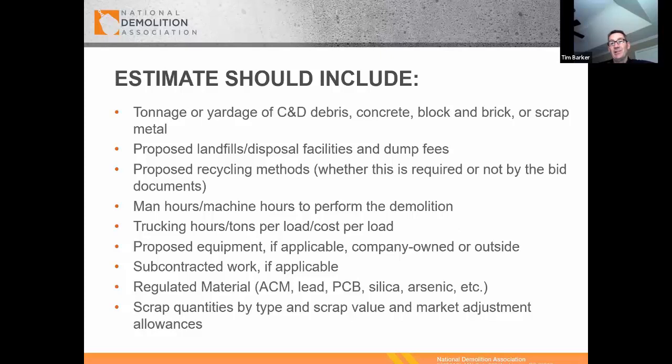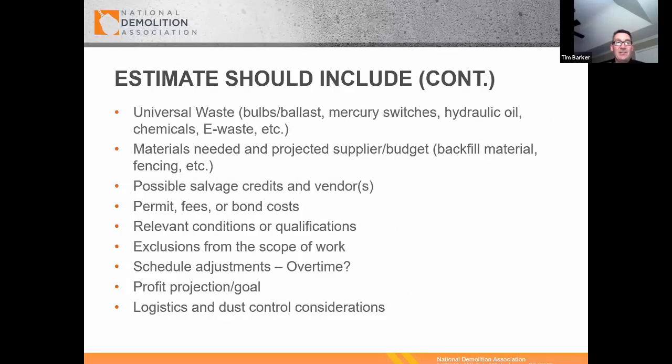An estimate should include, obviously, your quantity takeoffs for disposal material as well as recyclable material. Your man hours, your equipment. It should include, if you're using these subcontractors, clearly if there's any regulated materials, asbestos, lead, silica, PCB. Silica is going to be something that you're going to have to start dealing with on most projects, as usually you can mitigate it with water, some type of dust suppression. And then understanding the scrap quantities.